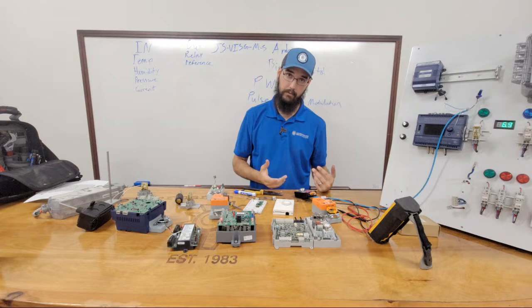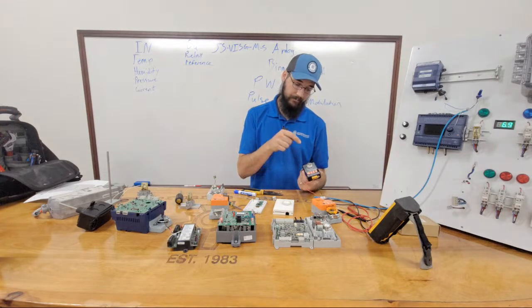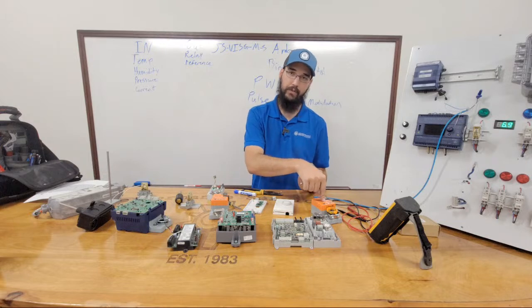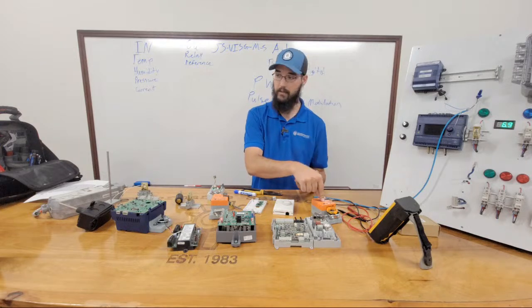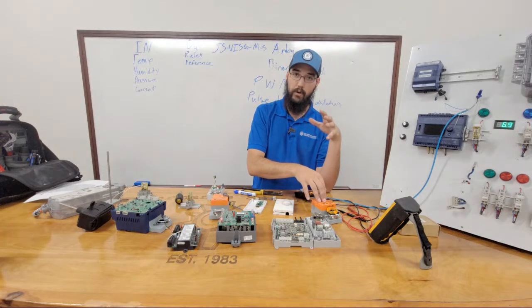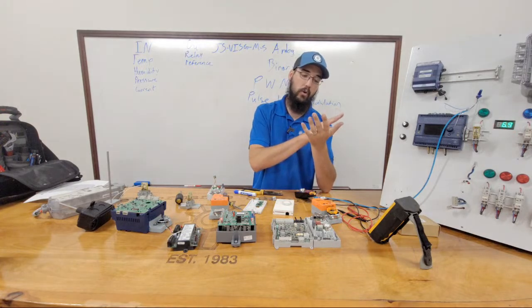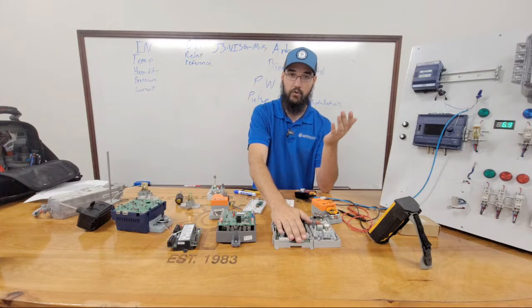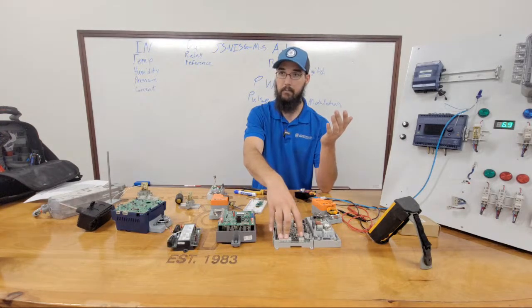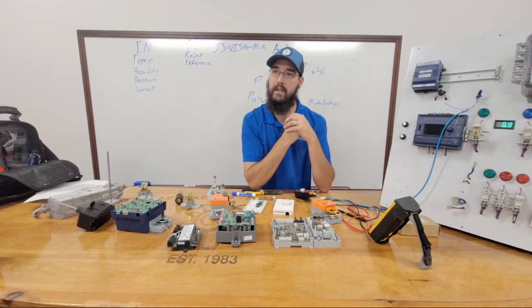you've got a little bit of a dilemma at this point. Okay? This is where having a voltage generator does help, because what's possible is if the internals go bad inside the actuator, it can create some kind of short internally, so that your VDC coming out of your controller might read 0 because the actual current load on this is next to nothing. So it doesn't take a whole lot to pull that voltage down to very little to nothing.